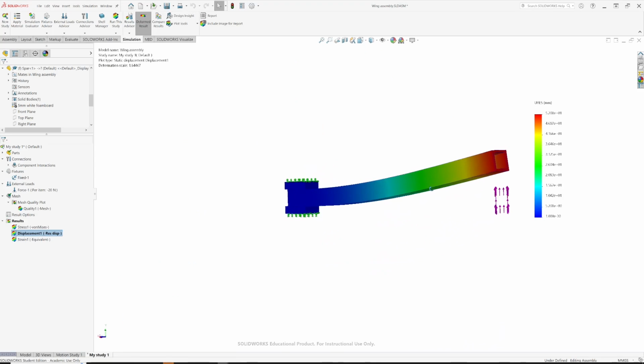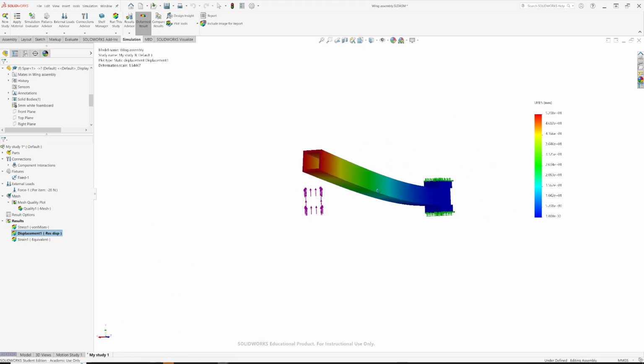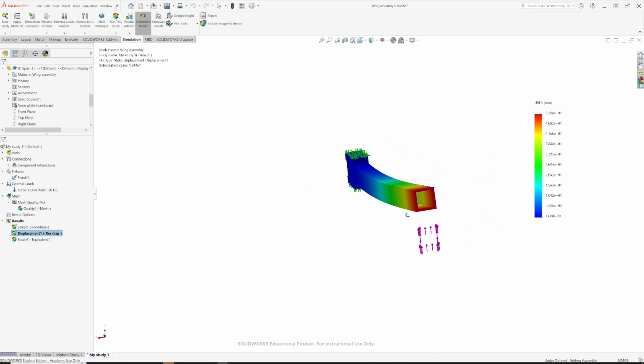So there's obviously quite a lot of moving parts between the Excel spreadsheet and this, but it's kind of showing everything is working. There's obviously uncertainties in the material properties, but if you use the same material properties in SolidWorks as you do in Excel, you should get about the right answer, which is encouraging. And while we're here, let's just check the stress level as well.